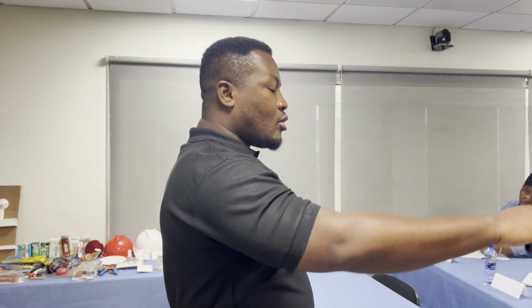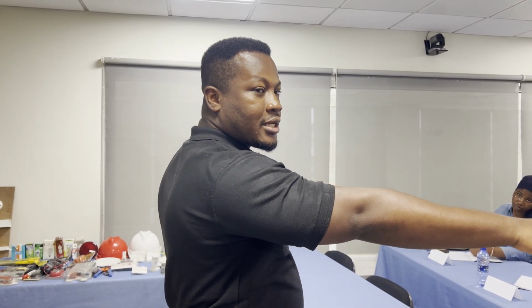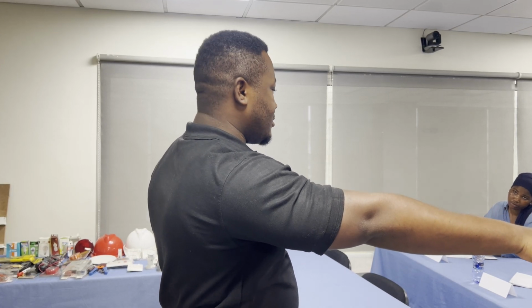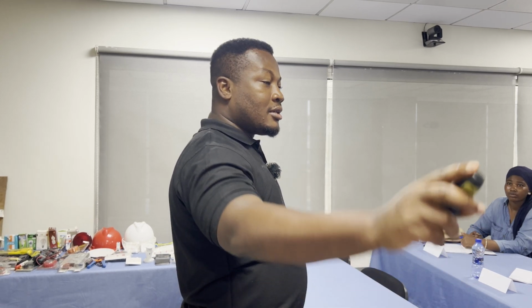The reason being that for a ring circuit, the advantage is that if there's a failure in, let's say, socket 2, people on this socket, let's say socket 7, can still have power. But for radial, if there's a problem here, the subsequent ones wouldn't have power.